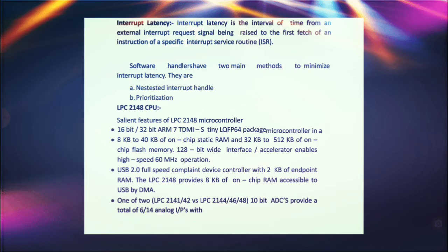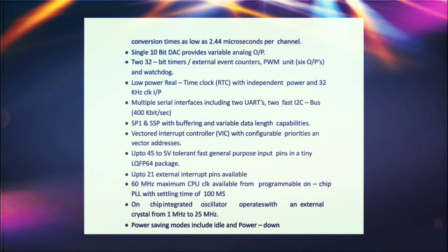USB 2.0 full-speed compliant device controller with 2 KB of endpoint RAM. The LPC 2148 provides 8 KB on-chip RAM accessible to the USB by DMA. One or two 10-bit ADCs provide a total of 6 to 14 analog inputs with conversion time as low as 2.44 microseconds per channel.